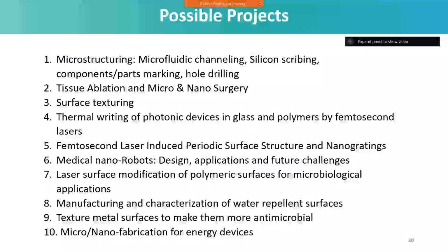And with that femtosecond laser, what are the possible projects that you can think about? One is microstructuring. I am not talking about optical microstructures. It is the structures that you can create at a micro level, and we even started working on different micro channeling applications, microfluidic devices. Either silicon scribing is possible, or tissue ablation and micro nanosurgery,